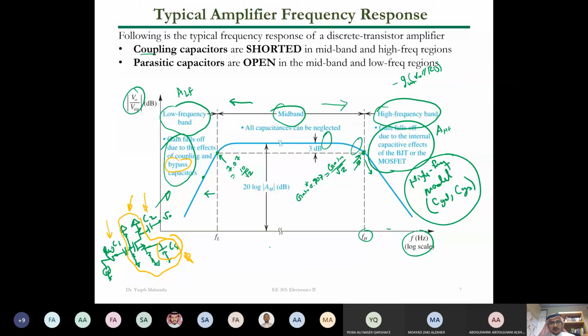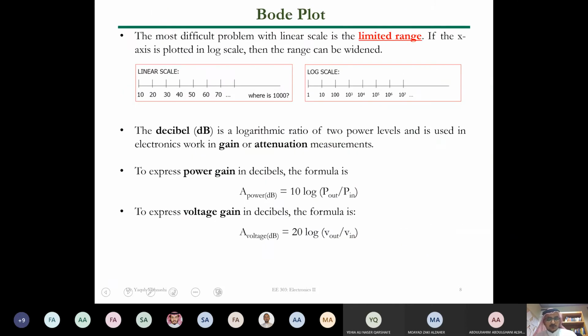We use the 30% reduction in the gain as the standard to define the bandwidth. In other words, in terms of power, you are losing half of the power at that point, and beyond that you are losing more than half. Okay, let's continue, guys.